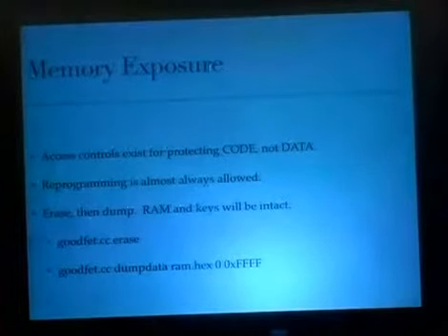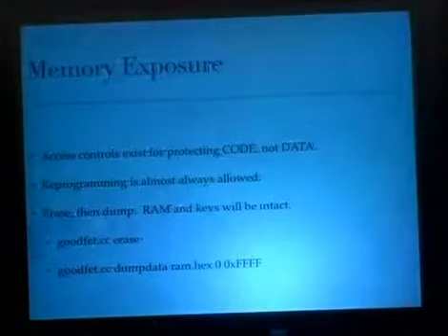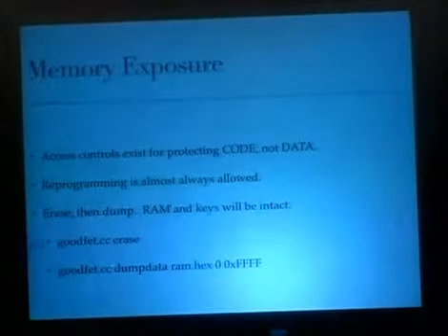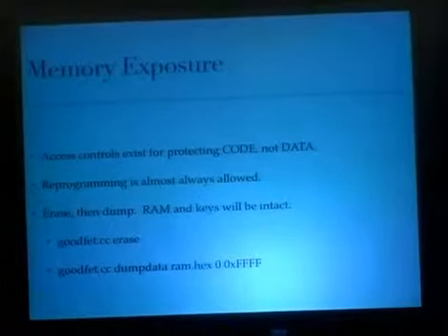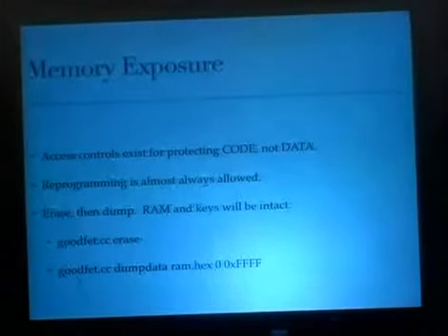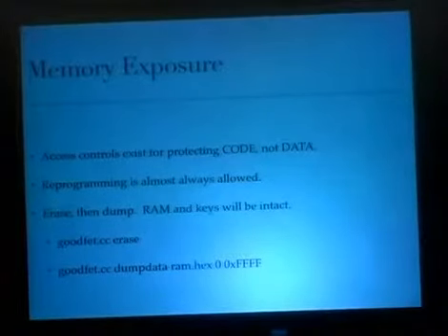As for memory exposure, because the access controls exist for protecting code and not data, they're just trying to keep you from copying a product. They don't really care if you can figure out which radio channel it uses. Reprogramming is almost always allowed. Before you're allowed to reprogram the chip, it wants to make sure that it's erased. So an unprivileged user is allowed to erase the entire device and nothing else. But what you can also do is erase and then dump.